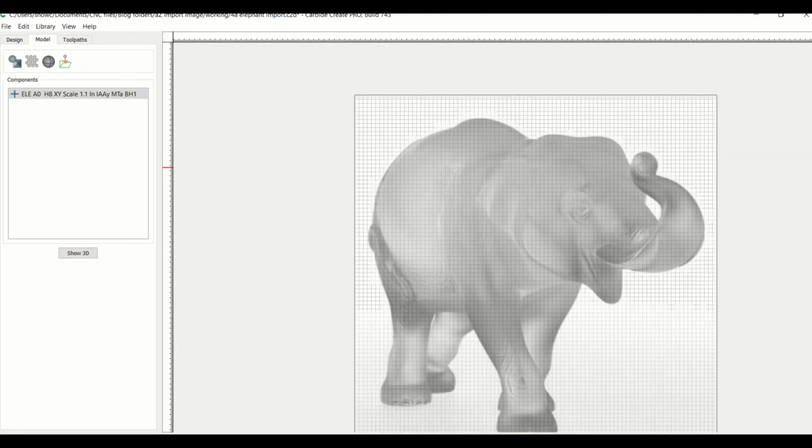Once you've closed out your model that you're building by hitting done, it'll pop up as a component as part of your build. What can you do at this point? You can right mouse click on it, and you can disable it so you don't see it as part of your model.